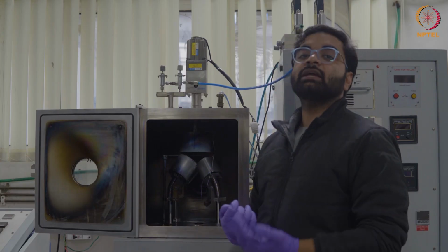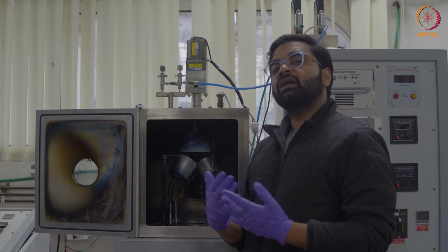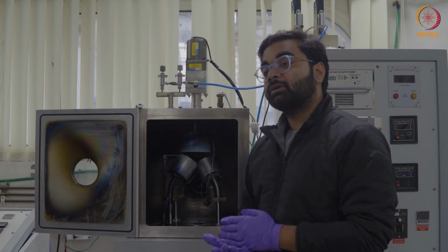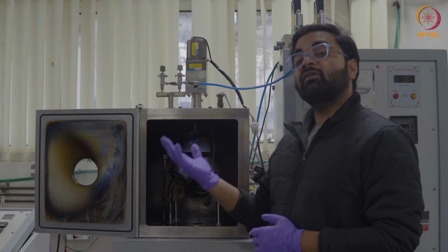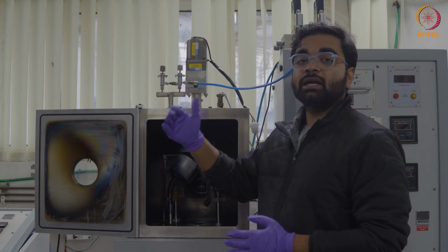For instance, if you are taking metals such as aluminum, nickel, or titanium, it takes 15-20 minutes to get a thickness of 3 to 4 microns. But silicon carbide is a very tough material, so at times it requires 10 to 12 hours to get a thickness of 3 to 4 microns. So we do it in steps to get that amount of thickness.